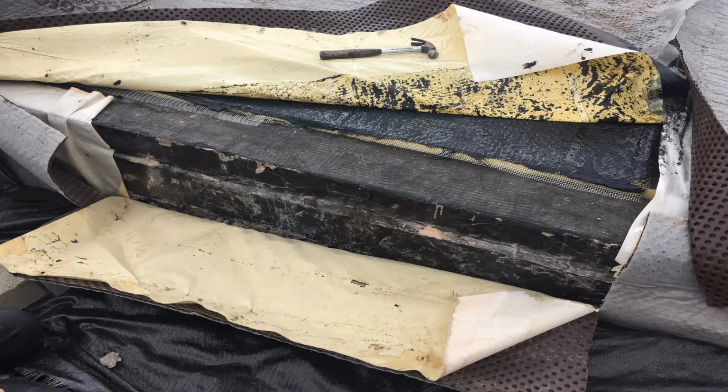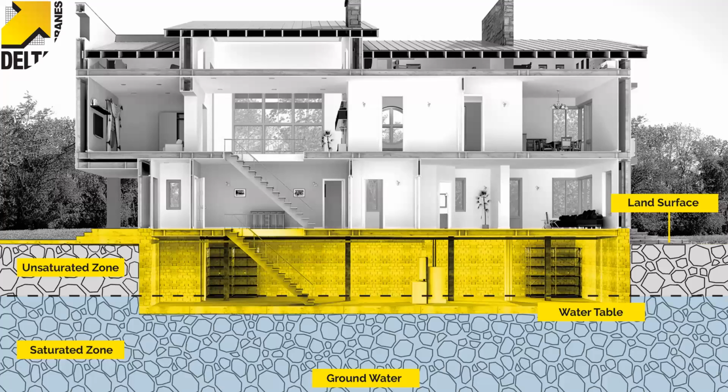So less than adequate workmanship, poor specification of the insulation, value engineering by the client, poor structural formation, if you like, of the retaining wall. And all these factors led to a disaster. Okay, so that's my favourite defects. We put that right in the end by using 2 waterproofing systems and substituting the insulation, and we'll talk about that later when I talk about open decks. So that's a defect. Lots of them.